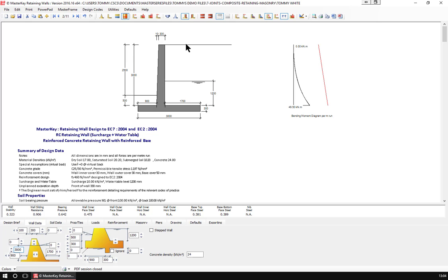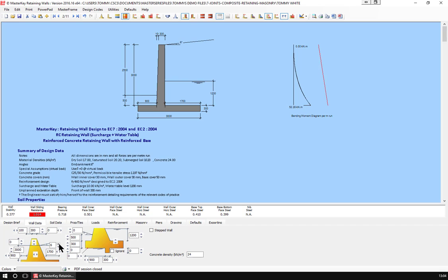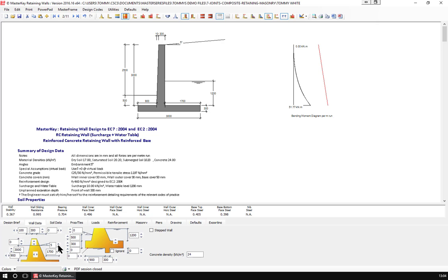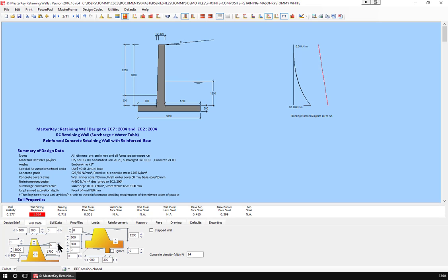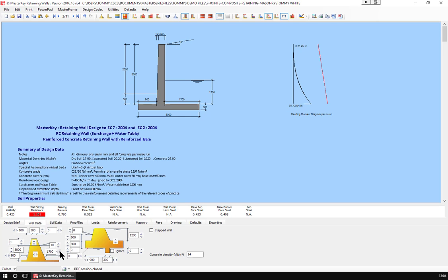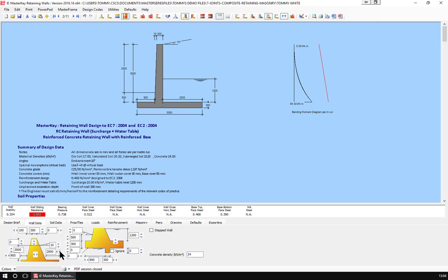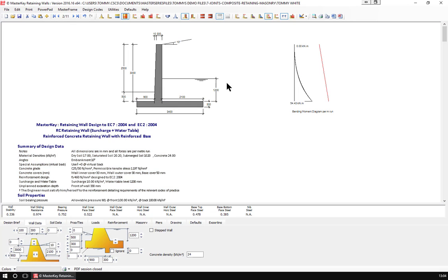We then have the back soil, and we'll see here that we're sitting with a soil slope of 0. We can increase the soil, as we can see very quickly. As we add in more soil, the wall suddenly starts again to fail in sliding, as we're getting more push than we are gravity on this wall. So if I was to go up to a 10-degree slope, I would need to lengthen my base to be 2.1 heel on the wall to make that work.